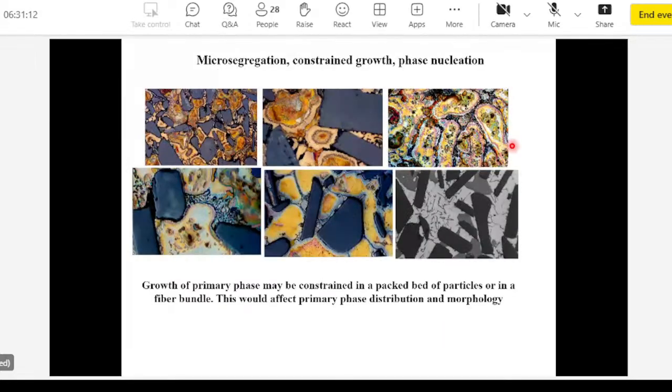And here we are looking at some metallurgical structure of composites. These colors, you can use special methods to color etch your samples. Each of these colors is a different chemical element. So copper, nickel, aluminum, all those will show bands of different colors. And this could give you a very clear visual picture of how microsegregation takes place between particles or fibers.